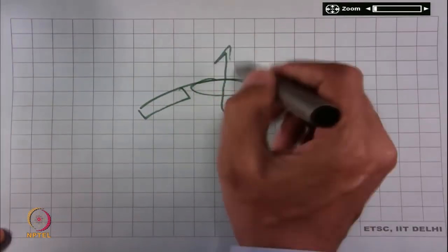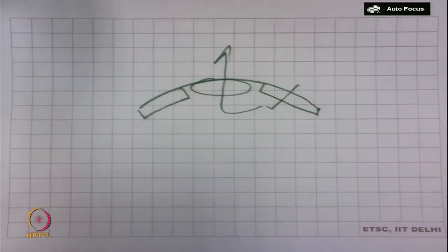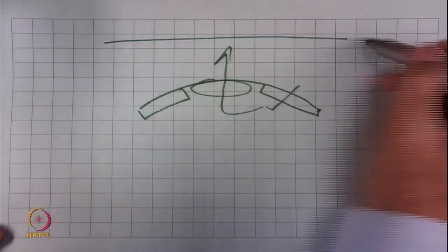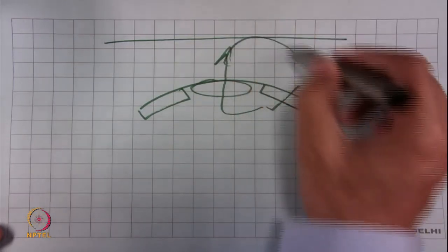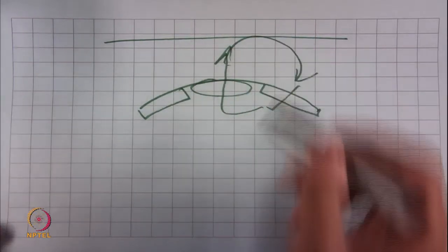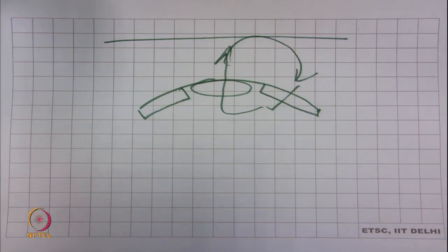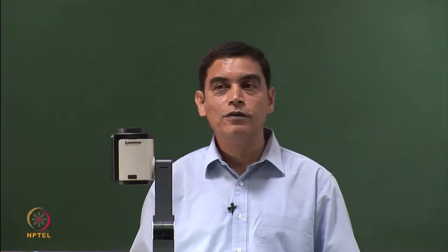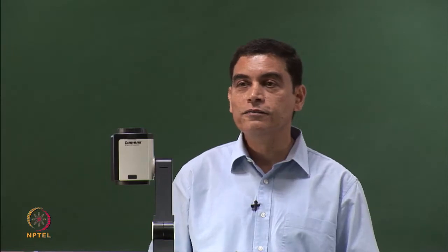So long as it is free to air with no obstruction on top, there is no problem. The moment you provide a shed, this air comes back in. So there is short cycling, and there is some robustness needed in the unit. So there is a need to change the test. So from 46, we suddenly were required to have the units deliver cooling at 50 degrees centigrade.